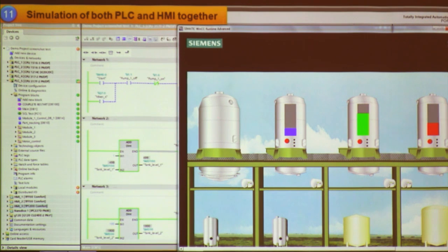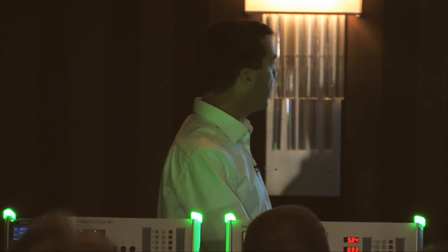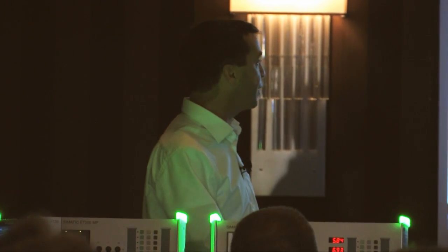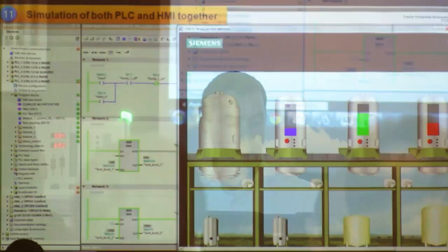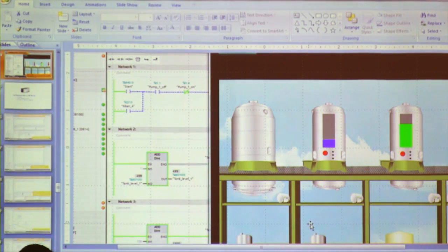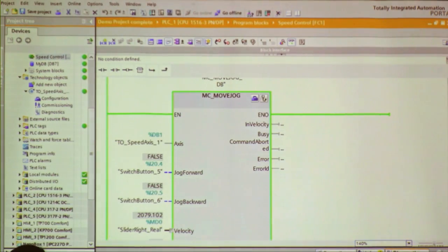And then, of course, no problem. For the other hardware that I have in my project that I don't have in this kit, I can simulate that 300 PLC and that panel that I don't have. I can simulate them offline without any hardware. I'm going to do that in a minute as well. So those are three things that we think can help in the commissioning phase and reduce your engineering time. Let's start with the trace feature, because I think this is definitely worth showing here.